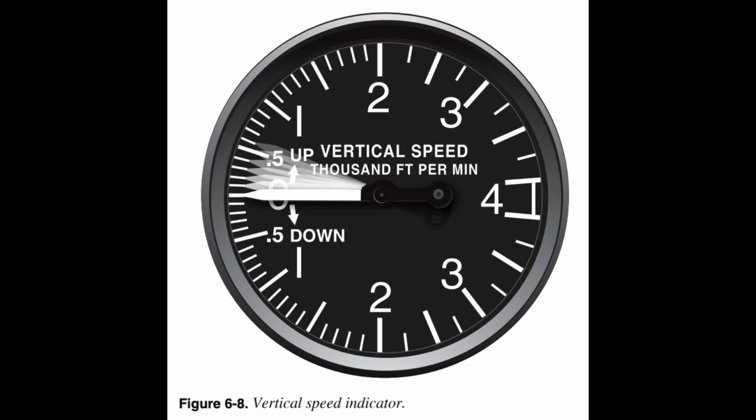In flight at a constant altitude, the VSI, sometimes referred to as vertical velocity indicator or rate of climb indicator, remains at 0. If the needle moves above 0, the pitch attitude must be adjusted downward to stop the climb and return to level flight. Prompt adjustments to the changes in the indications of the VSI can prevent any significant change in altitude. Figure 6.8. Turbulent air causes the needle to fluctuate near 0. In such conditions, the average of the fluctuations should be considered as the correct reading.